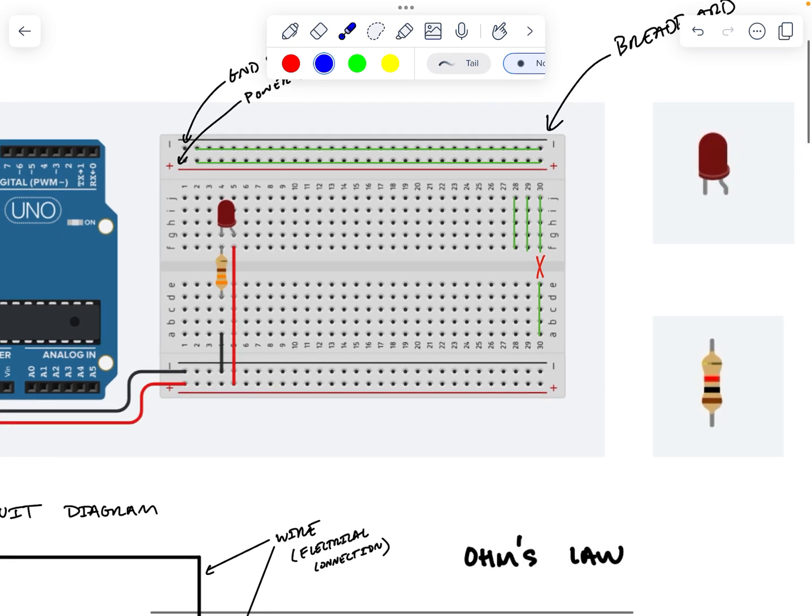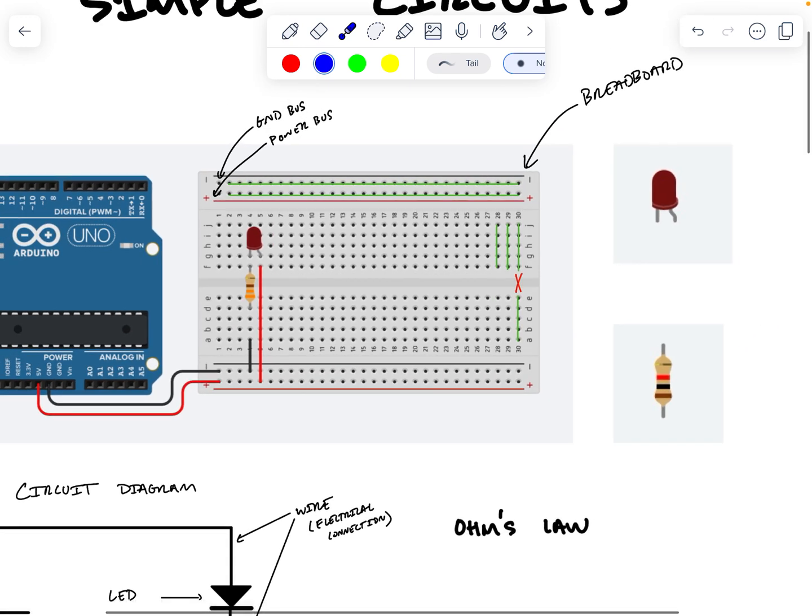Now, the breadboard is a rapid prototyping board, but there's nothing about it that says that this ground bus actually has to be ground. What determines that it is ground is that you plug it into a ground on a battery, and the only thing that turns this into a 5-volt power bus is connecting it to a 5-volt power source.